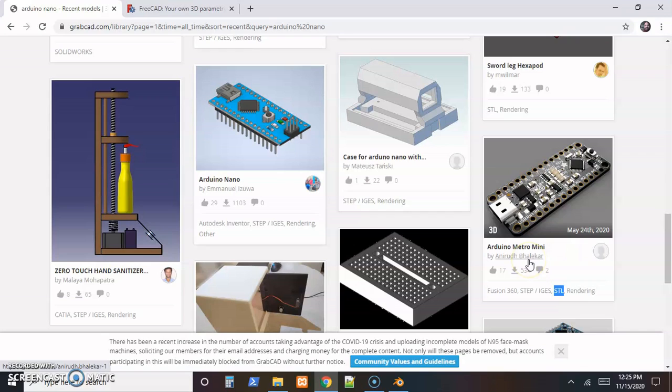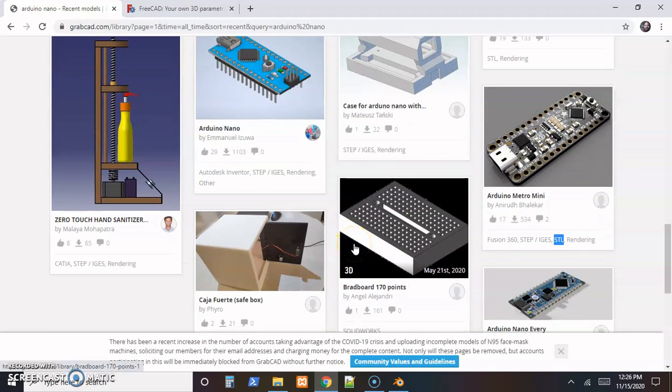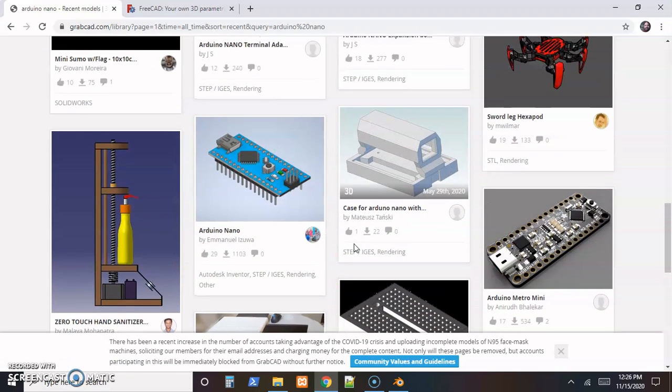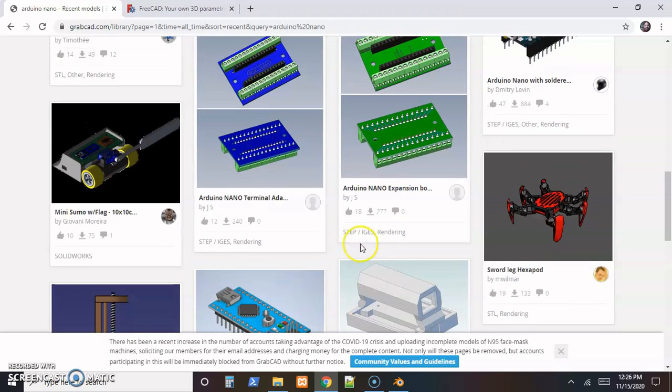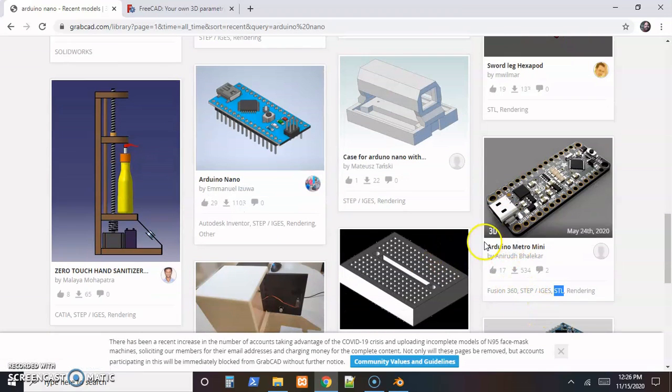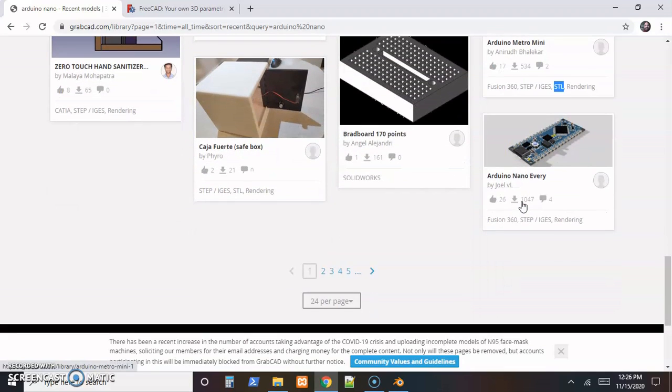All of the polygons are reformatted as triangles, so pretty much any 3D modeling software can deal with the mesh then. So there's a lot of STEP files. I believe that's SolidWorks, Fusion 360, Inventor. So a lot of parametric solid modeling files on here, really. But I just need a mesh to work with in Blender, so I can download that and convert it to an STL mesh on any of these. Because this one has an STL, but it doesn't have any pins connected.